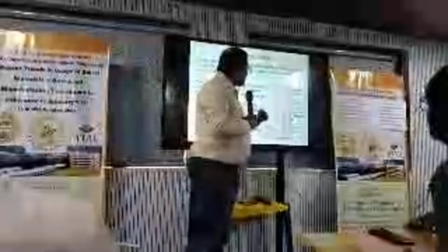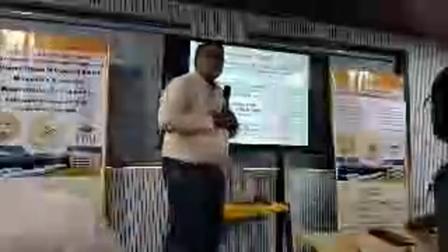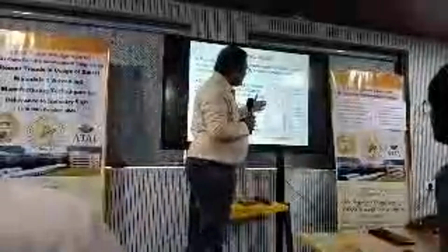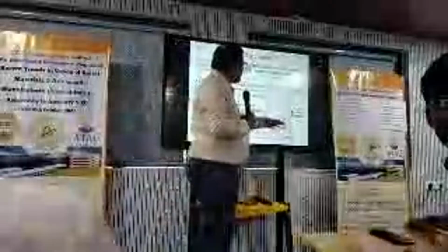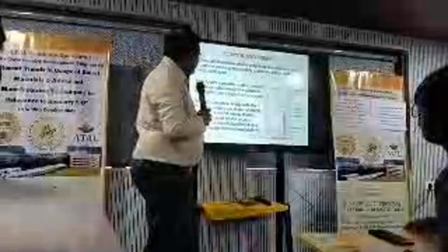Basically, this is the acoustic panel. There are 3 layers. If you see these panels, here is the impedance sheet. Outside is the perforated sheet. In between, the sound absorbing material will be there. When the incoming sound wave passes through this, it creates some voids. When it is passing, the sound energy is converted into heat energy in the sound absorbing material, and this sound energy will be reduced. That is the main aim of this acoustic panel.